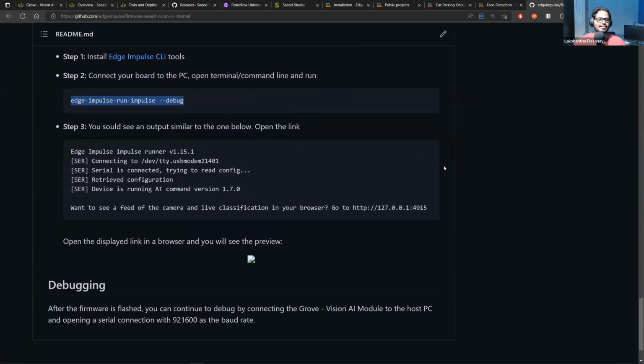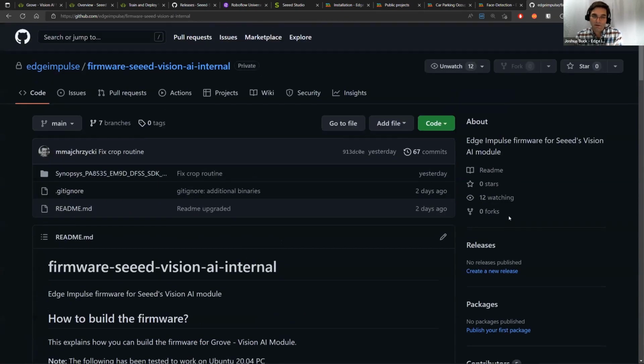So after this, if developers want to integrate this Edge Impulse SDK into their own application, they can use this. Yeah, and to add a point there, what the Edge Impulse SDK has inside it is a number of functions that are required to deploy the model and get it running and inferencing on the target. Yeah. And the output of that is a typedef struct from which you can get inferencing results such as bounding boxes, locations of the object within the image, inferencing time, etc.